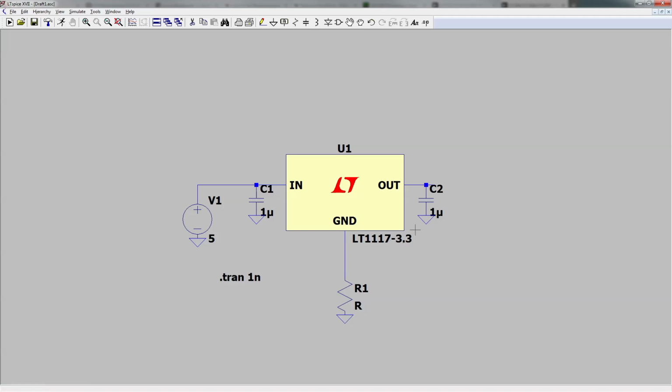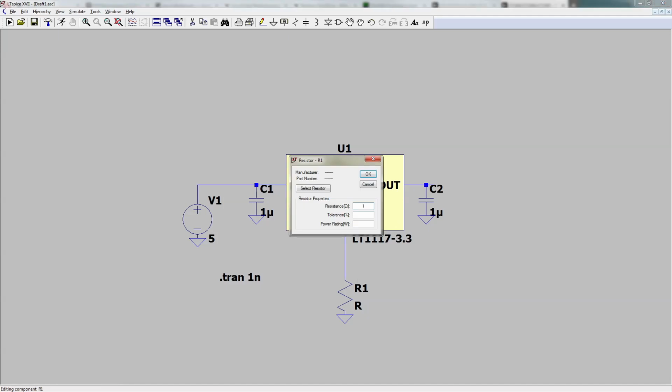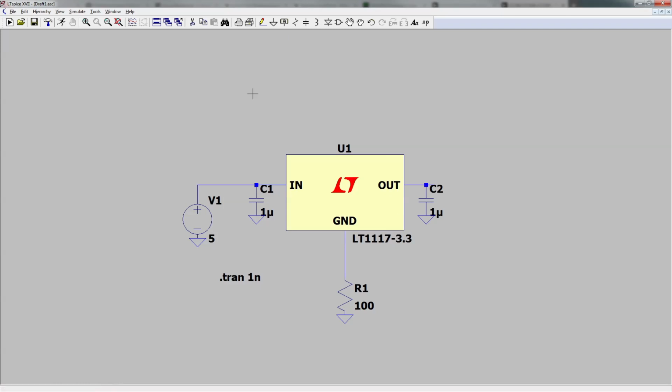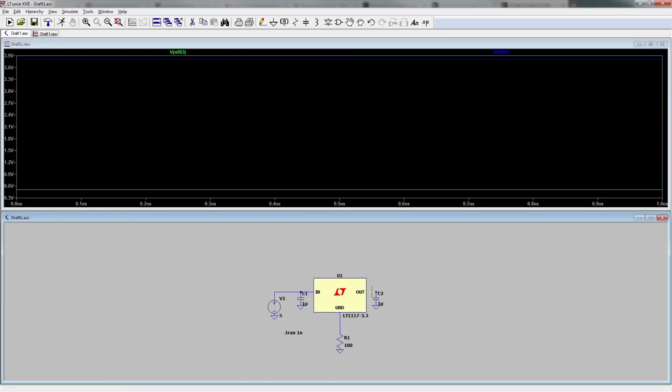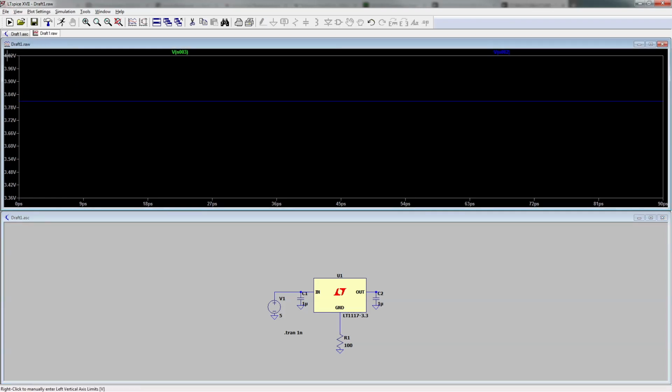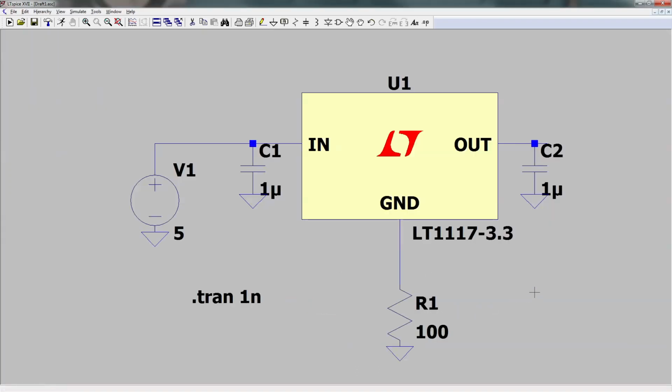But of course, with a real adjustable one, you can get better accuracy. So okay, if we assume here 5 milliamps, then 100 ohm here should give plus 0.5 volts. Let's see. Yeah, this is around 500 millivolts, and the final output is 3.81. Yeah, all as expected.